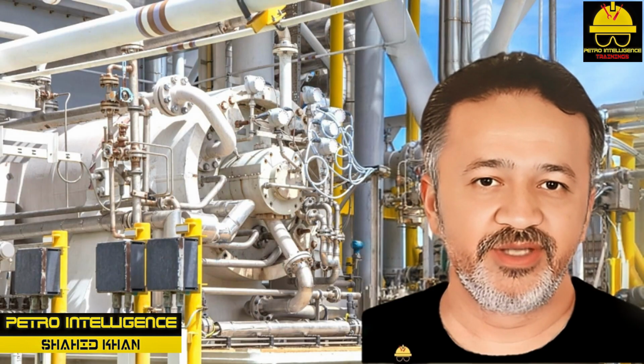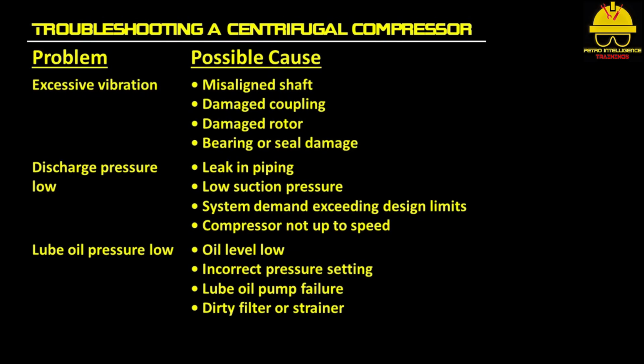Troubleshooting a centrifugal compressor. If there is excessive vibration, there might be a misaligned shaft, damaged coupling, damaged rotor, or bearing or seal damage. If discharge pressure is low, there might be a leak in piping, low suction pressure, system demand exceeding design limits, or compressor not up to speed.